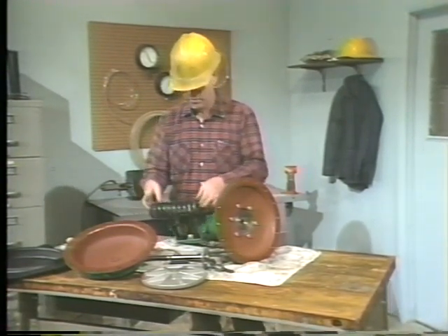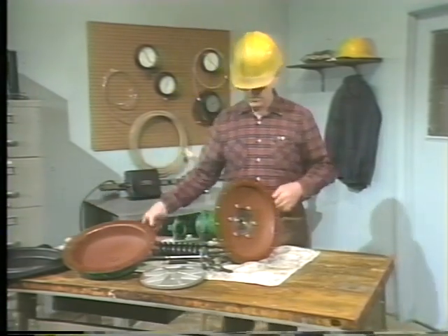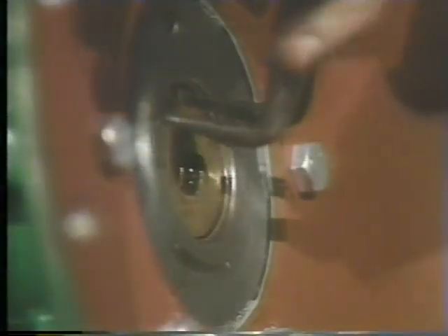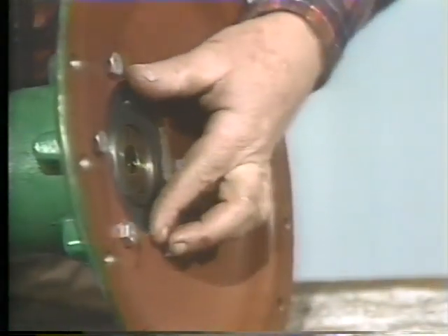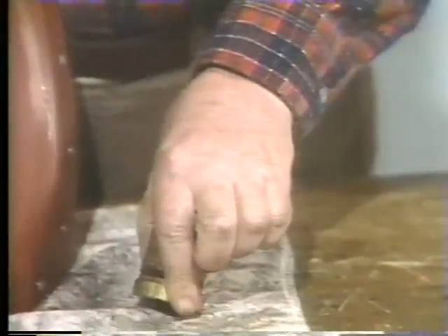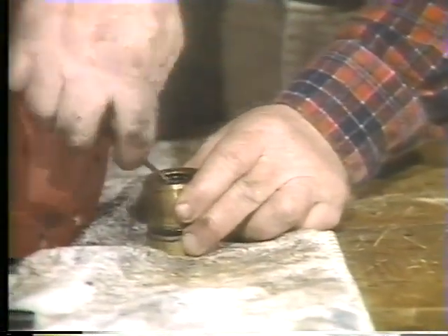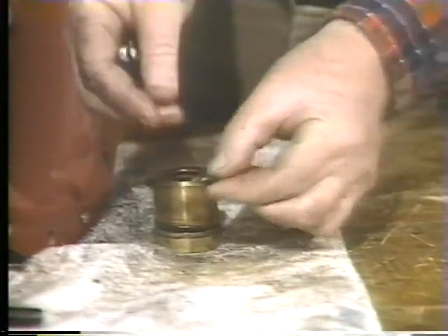After the technician has removed the diaphragm and stem assembly from the actuator casing, he can remove the spring. Now he can get to the O-rings by removing a retaining clip and pushing out the stem bushing. The O-rings are mounted inside the stem bushing, one at either end. As they are removed, they should be inspected for damage or wear. If they're worn or damaged, the O-rings must be replaced.